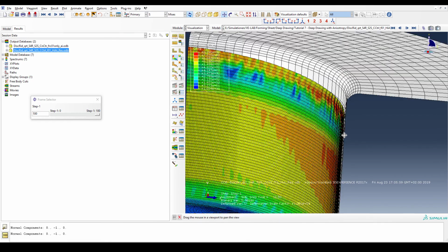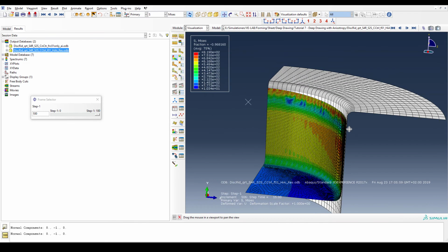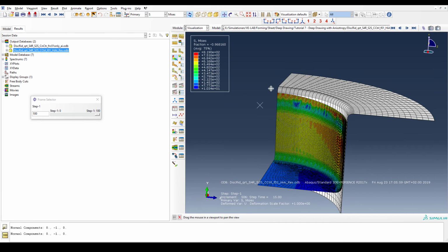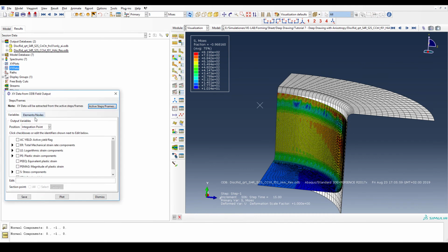So you can see that simulating with this fixed distance might not actually be what you do in reality, because usually the blank holder is force driven and you apply a constant force, right? So again, this is really a thing that you should play around with, and keep in mind that this heavily affects how the shape of your final part will look like. I just wanted to point out one aspect here.